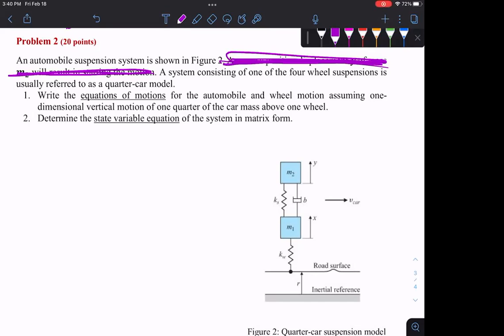And you can control it then, because then you will design a controller that will make that response behave the way you want. So designing your controller highly depends on what your system is and what is being applied to your system from the environment. So you're never going to get a problem that has everything solved for you. Hey, there is an internal F of t applied. These two are your state variables. This is your output. Most of the time you will define that, which is system identification, simulation problems, then you'll solve the control problem, right?